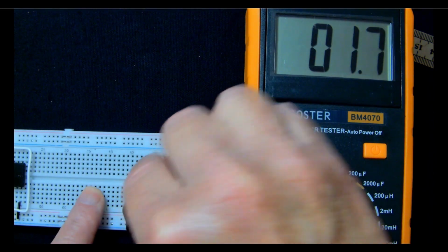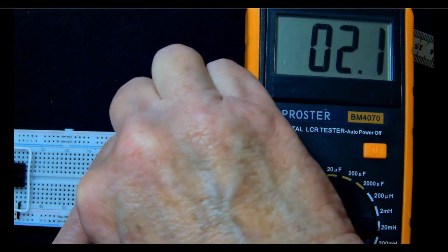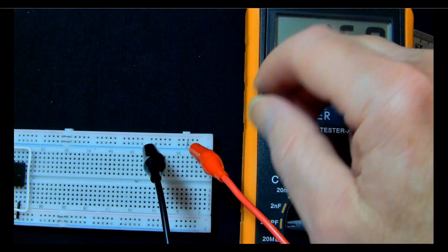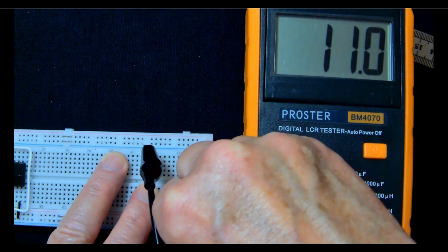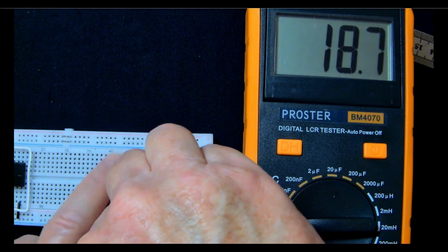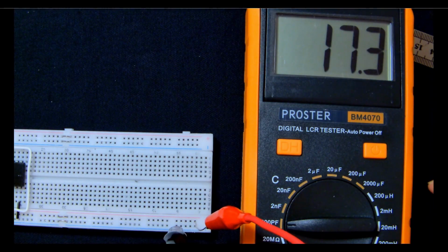And the reason that the ones on the power rail are higher is because they're a lot longer. So the plates of the capacitor, which are effectively the rails themselves, are much longer than the vertical strips. They will have a bigger value. And in fact, that one has got a higher value than the top.